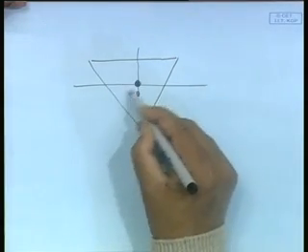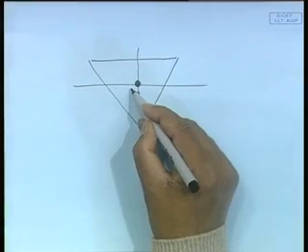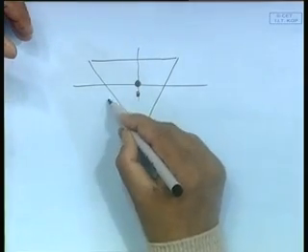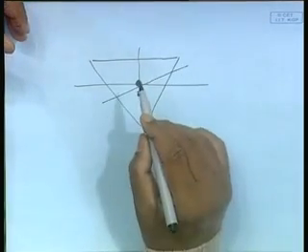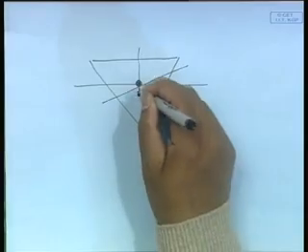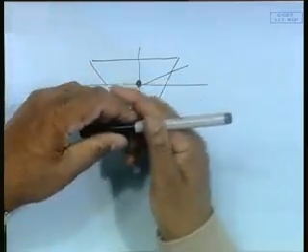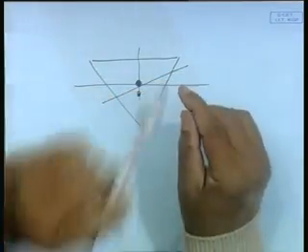You know all that if the angle is a little large, this will not pass through here, it will pass through somewhere else. That would imply that if I were an experimental device and I fix this point somewhere, if I heeled it, this point will try to either go up or go down, agreed? Because underwater volume has to remain constant.